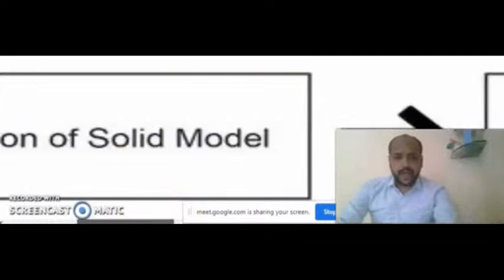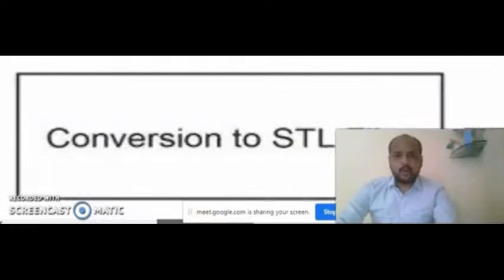For example, you want to create a prototype of a spur gear. So you should draw a solid model of a spur gear in a CAD software, in a computer aided design software. I am specially repeating the word CAD software. So you can draw that model. This is the first step. Now next step, you have to save that model into STL format.